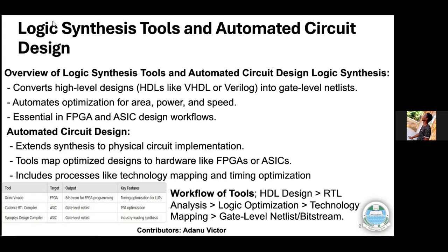Now, here it says that it converts high level designs like hardware description languages such as VHDL, which we're treating currently, or Verilog, into gate level netlists. So kind of like a series of zeros and ones that maybe the FPGA or the ASIC can understand.